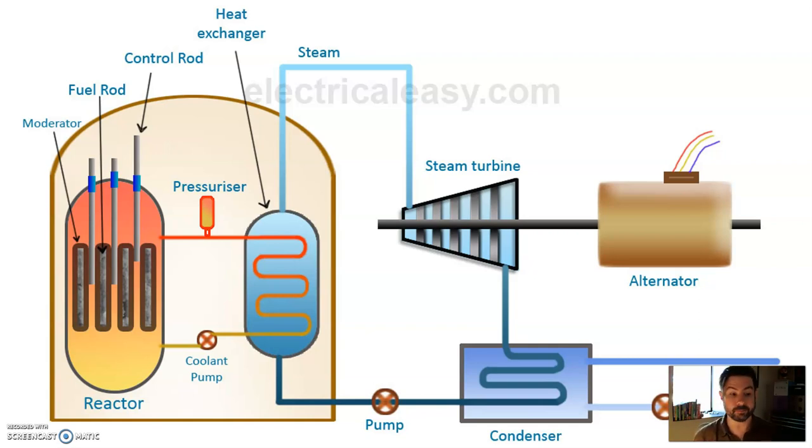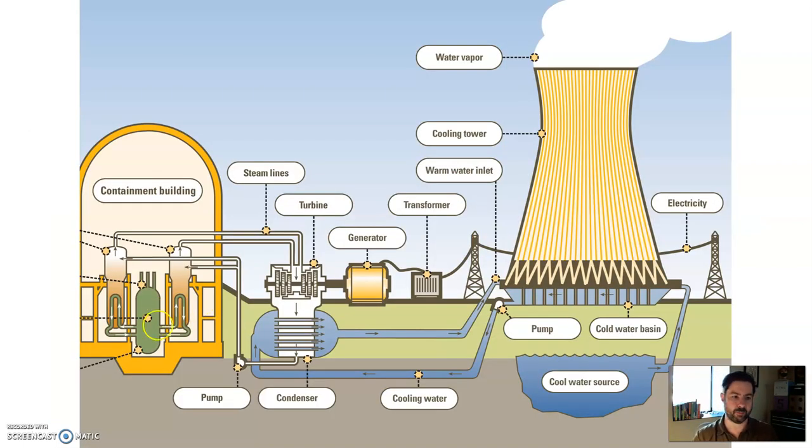You would have a meltdown when you can't control the reaction. Think of Chernobyl. So they have to input control rods, usually made of lead, to help slow that down. It kind of puts the brakes on. That lead absorbs some of that fission material to slow down the reaction. So we lower these control rods, put them in or pull them out, depending on if we want the reaction to slow down or speed up, depending on how much heat we want to generate to create steam, steam to spin a turbine, turbine to spin a generator to generate electricity. So that's how nuclear power plants work.